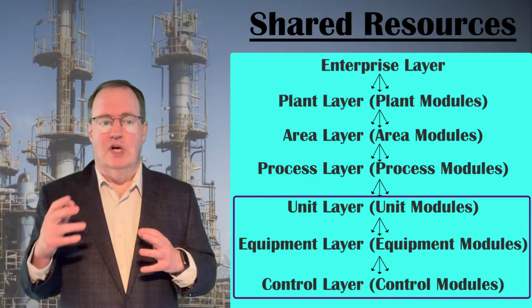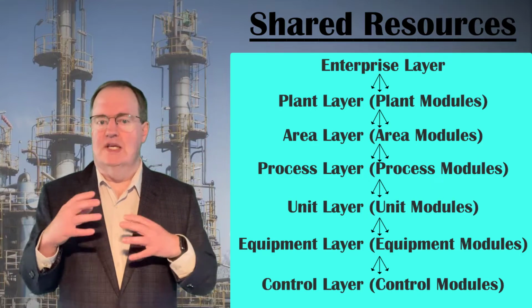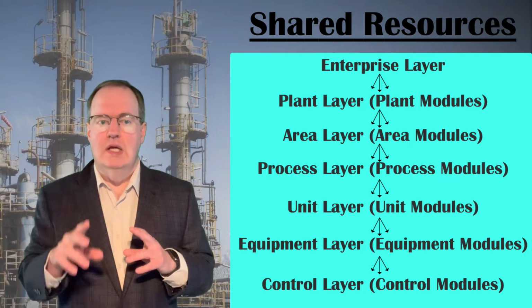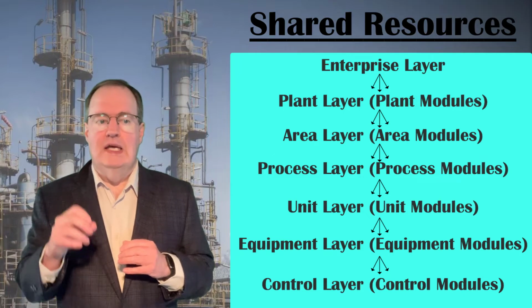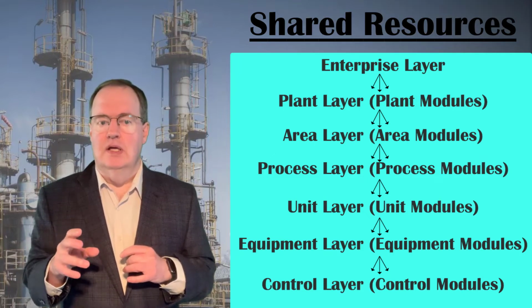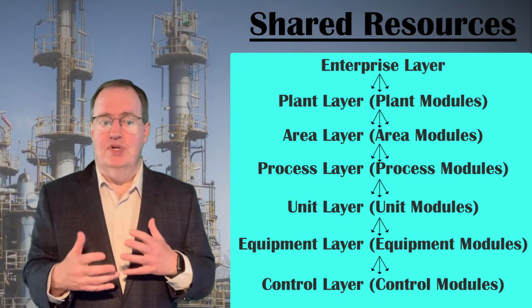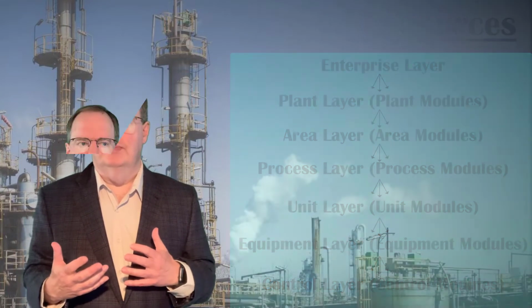Above that level, the questions of control are mostly problems of scheduling, logistics, and the optimization of both, which is beyond the scope of this course. But a problem that is typically addressed within process control is shared resources, a resource that is outside of a unit because it is shared by more than one unit. Typical shared resources include storage tanks and heating or cooling utilities.